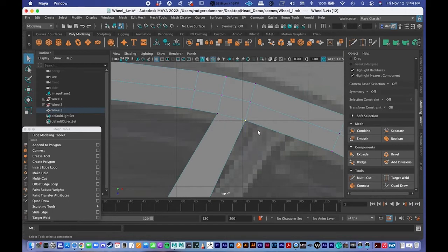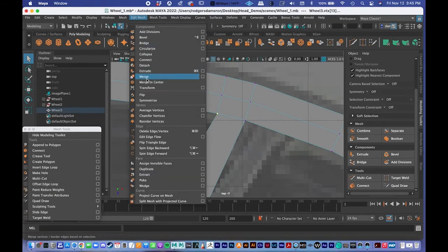So that snaps the vertices into the same place here, but you see when I click on it and then drag, there's still two vertices there, so they're not welded together yet. To weld them together or merge them together, you need to make sure to drag and select like this for that to merge these two vertices. And this is the fourth step, or the last step here, and it's this button right here, merge, or you can go up to Edit Mesh and Merge right there.